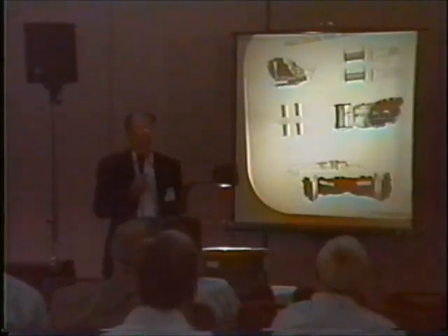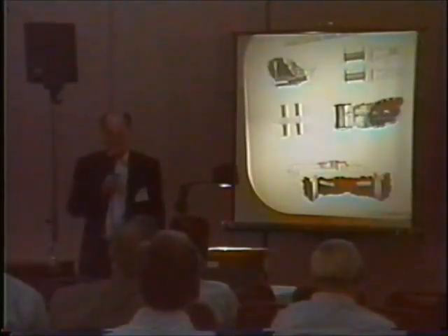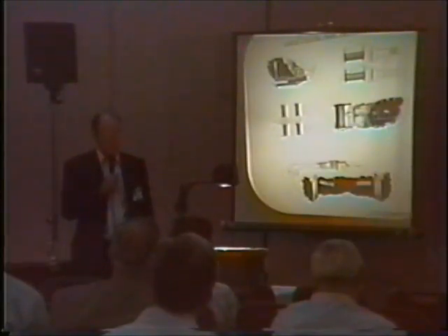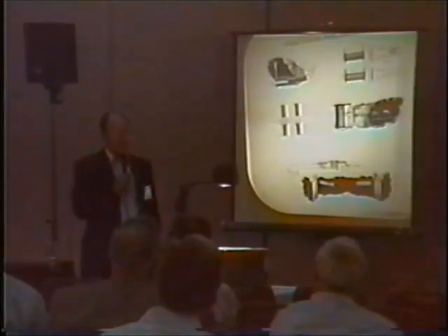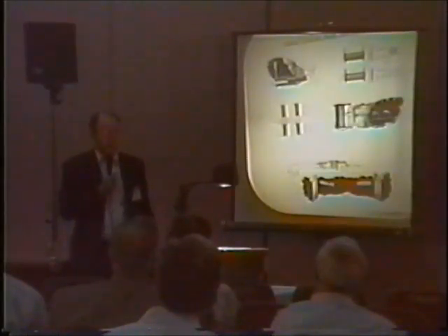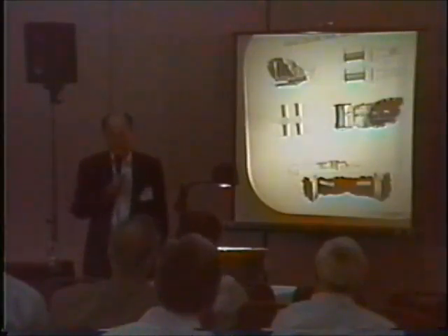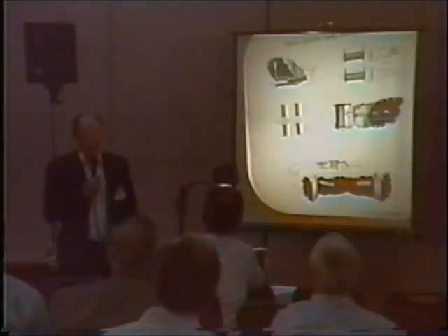And where you go to from there, depending on the amps that you want to be bothered with, you use a very heavy wire, maybe a size 4 or something like that, or maybe even size 2 or 0, and you make these things quite large and heavy, and then you make your L1 coil out of rather heavy stuff also. And the net result is when you pump the capacitor bank with this, you've got so many amps that you have trouble controlling them. This operates at 60 cycles per second with no iron?